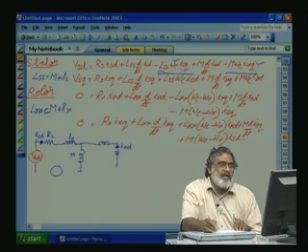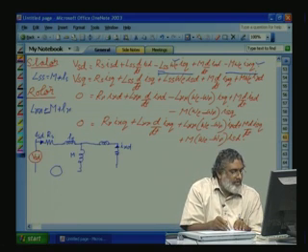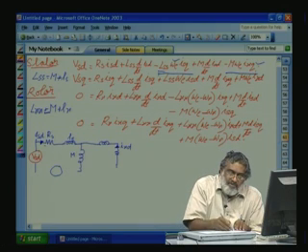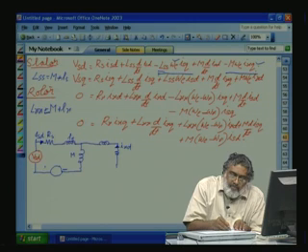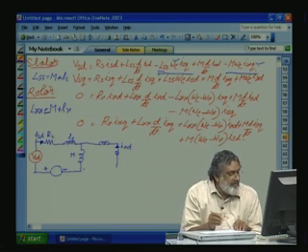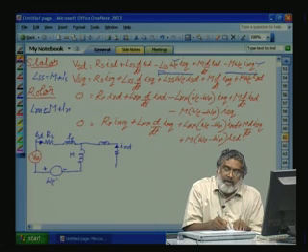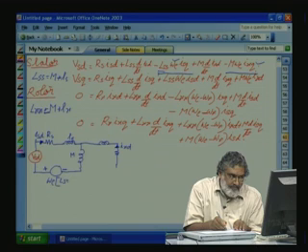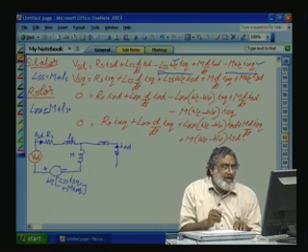That means current flowing through the Q axis equivalent circuit, these two, and this is minus. That shows we have taken current entering as positive. So, this is minus, meaning current ISD comes like this. So, current entering is taken as positive. The term is like this: a function of omega rho multiplied by LSS ISQ plus M into IRQ. What is this one? We will come to that later.